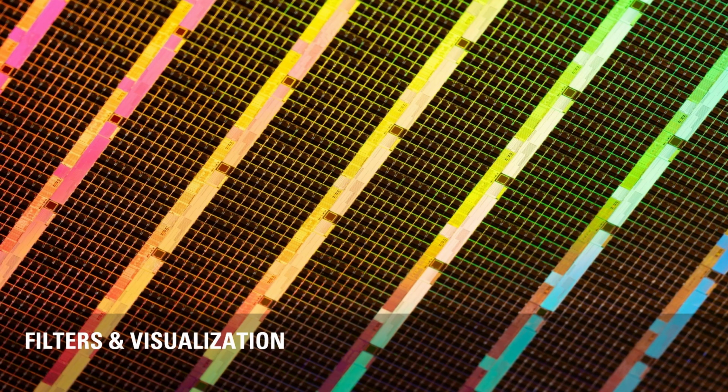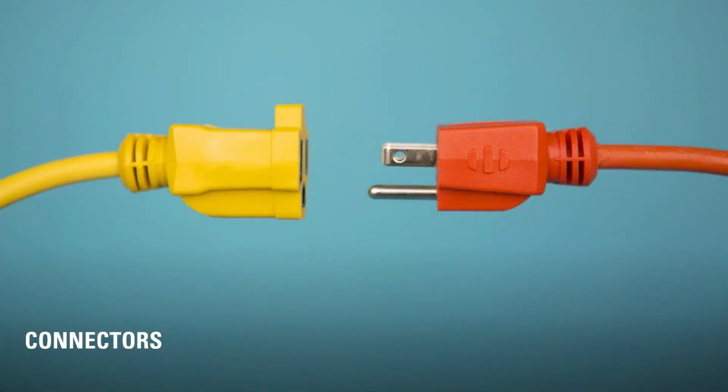Filters and visualization. Filters for systems. Filters are essential when working with MEP systems. They allow you to visually separate system types by color, pattern, or line style. For example, you could create a blue fill pattern for mechanical supply, green for mechanical return, red for fire protection. Filters can be based on service type, system type, classification, or any common parameter. This dramatically improves visibility and coordination within crowded service zones.